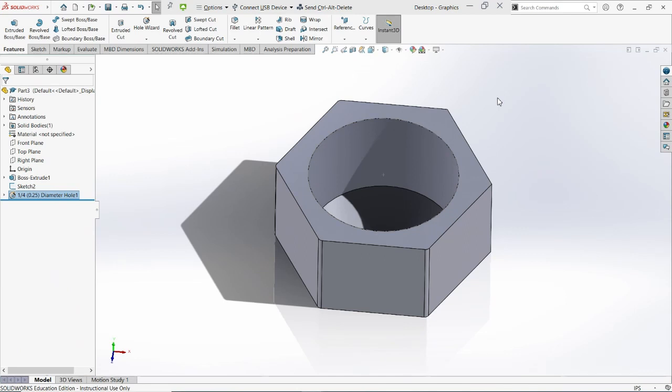So we revolved both of those features at the same time around our axis. I'm going to add bonus points because we then modified that feature to better fit what we think of as a pencil by creating that hexagonal shape and extruding away everything that we didn't need.